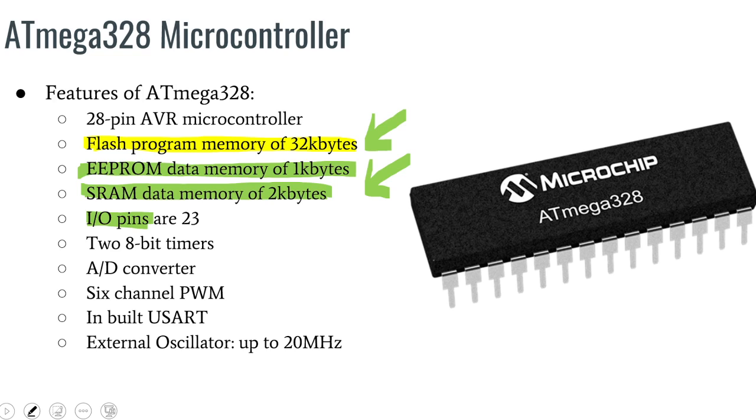Then in addition to that, we will have other computational components like timers, analog to digital converters, sometimes pulse width modulation components. So we will have various different components like that, which we will consider whether that is suited for our particular application. So when we are choosing a microcontroller, this is just an example, but we will look at the available microcontrollers and choose based on the specifications to see if that is suitable for our applications or whether it is not suited.